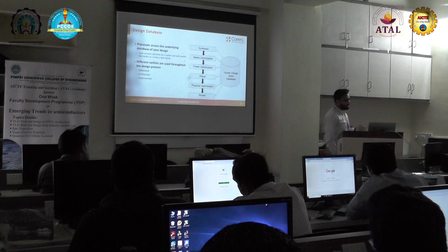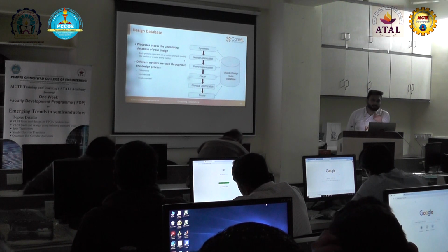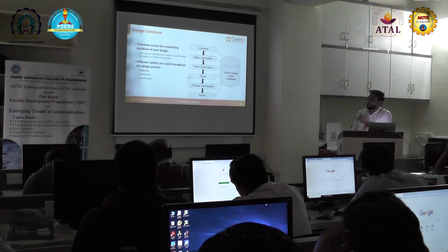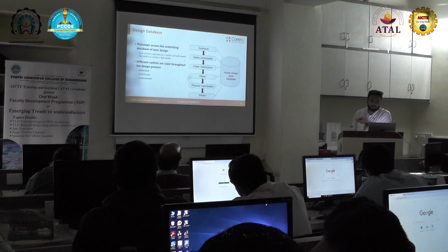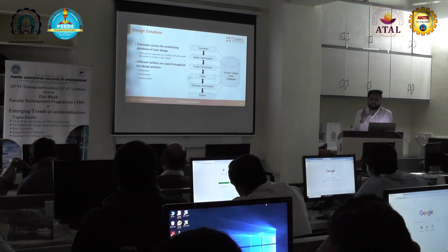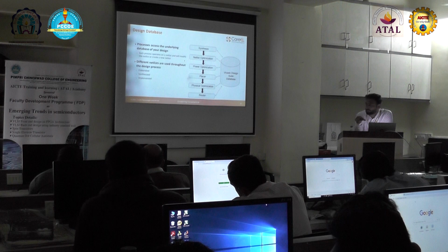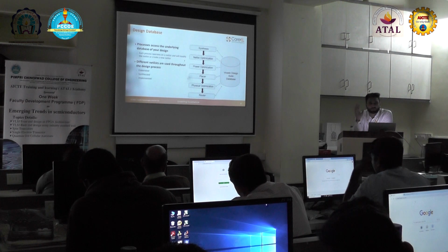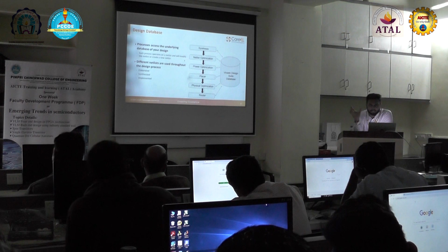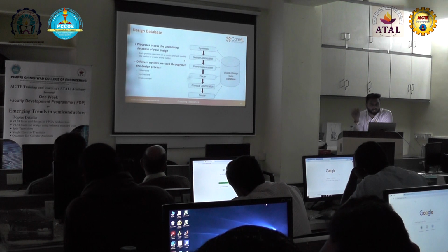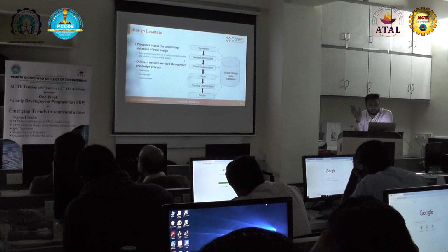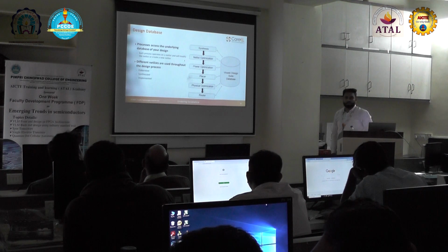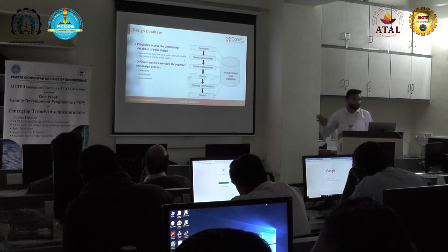It is created by taking as input the HDL code you wrote. It will take the HDL code and compile it. Then it will create the netlist. It will give the netlist for elaboration, synthesis, and implementation. For those three steps, the netlist is very important, as by taking the netlist only, it is going to do all the processes: placement, routing, optimization, synthesis, schematics, all will be done by taking the netlist.